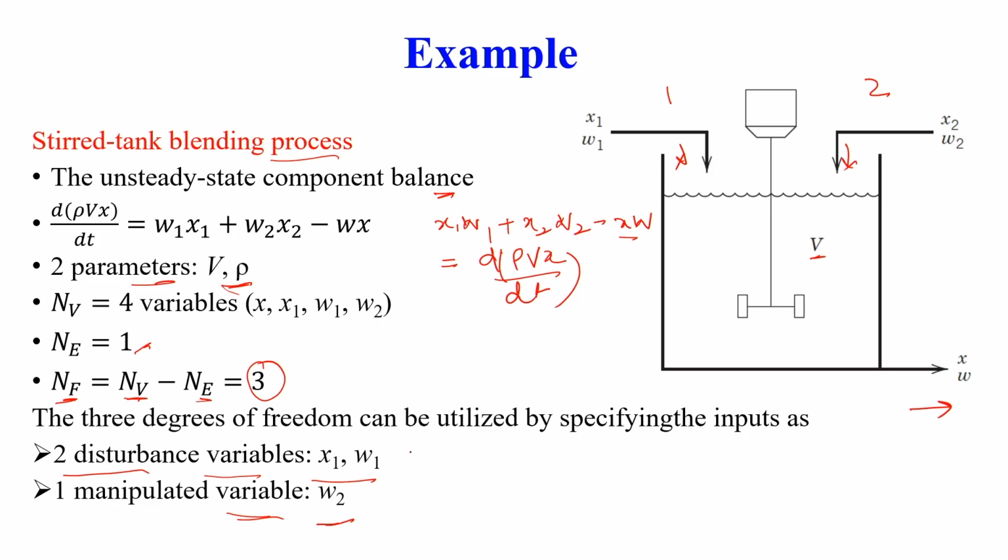So we are having these 3 parameters, and it is matching with the degree of freedom. If it is 3, it means we can fix the 3 parameters, or we can say these 3 more parameters need to be specified to define the system. In this way, degree of freedom helps us understand what the input variables are that can be considered either manipulated variable or disturbance variable.